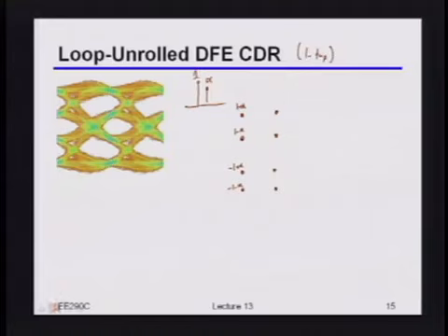So let's start with the simplest thing. Let's say I'm just transmitting a clock pattern, meaning I'm just sending 1, 0, 1, 0, 1, 0 at the full data rate. If I was doing that, what would be the arcs that I should draw in here? If this is the previous bit and this is the current bit, which analog levels can I start from in the previous bit, and which analog levels can I end at in the current bit? And by the way, I'll give you a hint for a clock pattern: the previous bit is always different than the current bit.